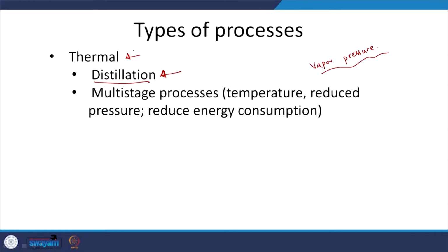But in general this is not widely used, at least for desalination. That is one aspect to keep in mind. And as mentioned here, it is a multi-stage process, typically at elevated temperature and reduced pressure. Why do we want that? We want to look at decreasing the vapor pressure. Again, what is the key aspect? Because I want to reduce the energy consumption. If not, I need to provide more energy for that heat of vaporization. So, that is the relevant aspect here.